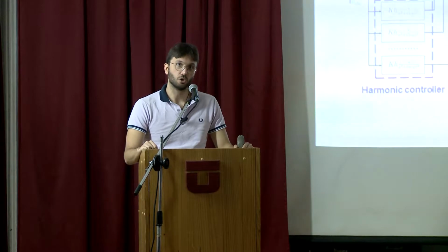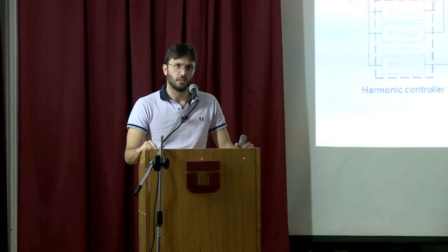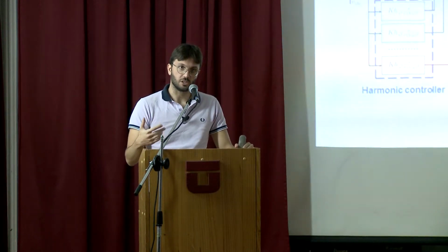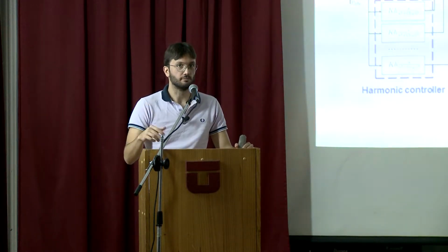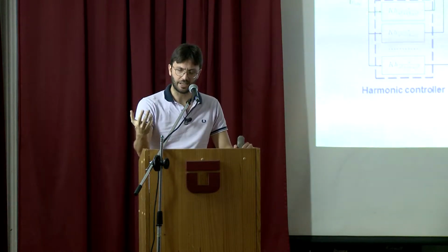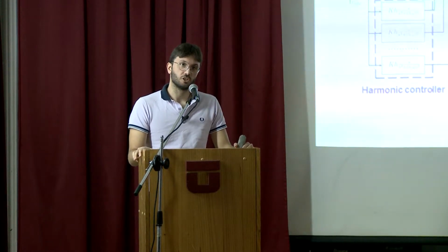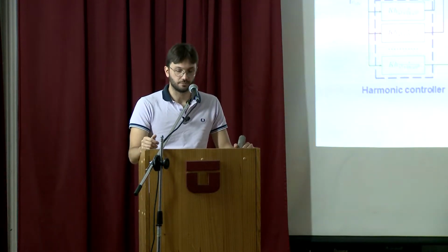The grid has a lot of power electronics converters with diode rectifiers, with harmonics. Also many transformers saturate, so they inject harmonics into the grid. Basically the low voltage grid is a very nasty environment.